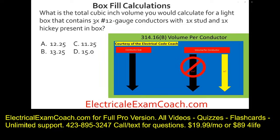What is the total cubic inch volume you would calculate for a light box that contains 3 12-gauge conductors with 1 stud and 1 hickey present in the box? For this one, we're going to go to table 314.16(B). We know that each 12 is 2.25 cubic inches. Now let's count our conductors. We know that we have the 3 number 12s originally, but now we have to deal with the studs and the hickeys. Our code states that each stud and each hickey count as 1 each based off the largest conductor that's in the box. In this case, we only have number 12s, so they're going to be grouped with the 12s. So that lets us know that we have a total of 5 number 12s.